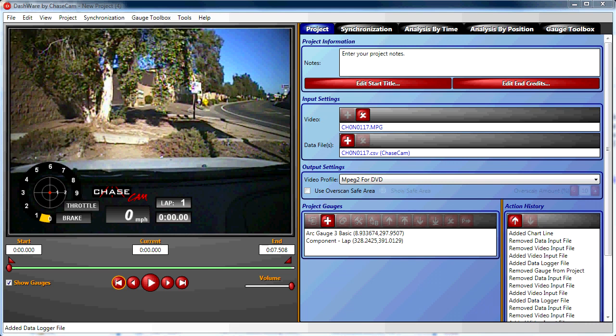In this video, we're going to show you how to take data that is collected via the sensor input for the DM10 data module and have it appear in DashWare. We're going to use the throttle position sensor data today for our example, but this would apply to any sensor that is plugged into the sensor input on the DM10 data module.